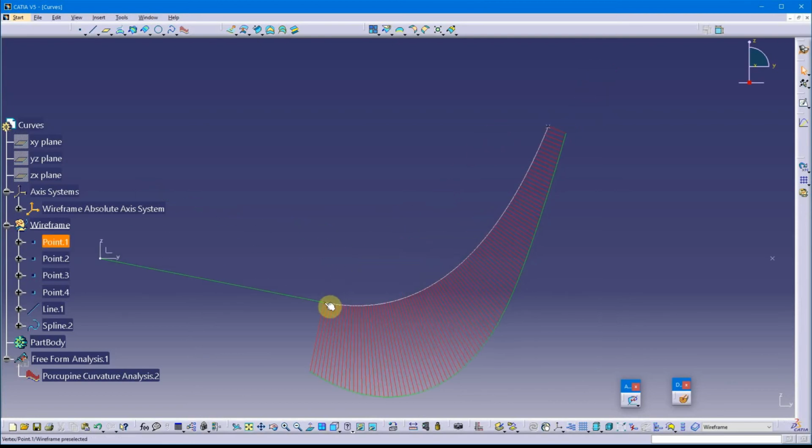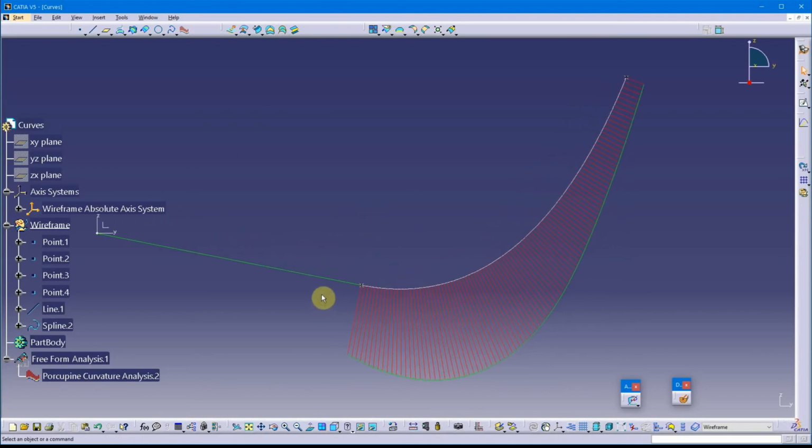So you might think to yourself, well, I've got 2 points. A spline between 2 points is a first degree curve. You won't have any continuity, but I added a tangent continuity on the end here. By adding that tangent continuity, I added a degree to my curve. Between 2 points, that would be a first degree, but when I added the tangent continuity, that added another degree. So this curve is a second degree curve with tangent continuity across this point. So that is G1 continuity.